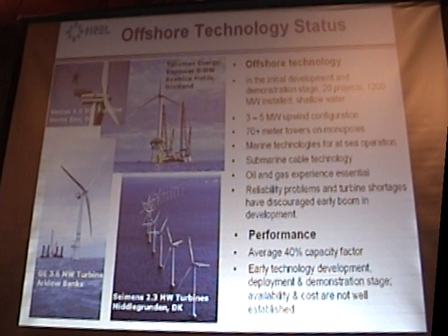But here's what I've been working on. It's offshore technology. The status today is that it's all in Europe. There's nothing going on in the United States except for there are several projects planned. The machines are bigger because we're not constrained by transmission. The parts for machines get so big that you can't ship them over highways and you can't lift them with conventional cranes. So offshore, that's not the problem because the cranes are bigger and we can barge everything everywhere.